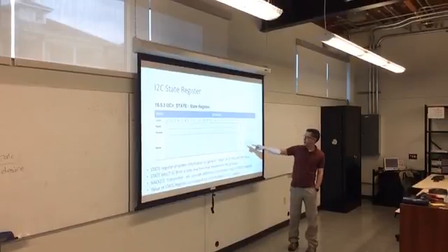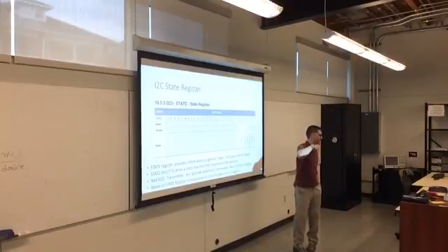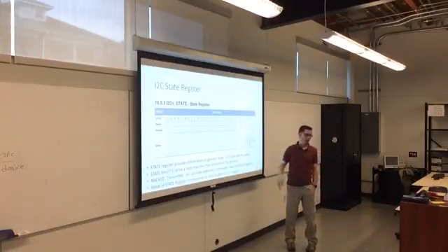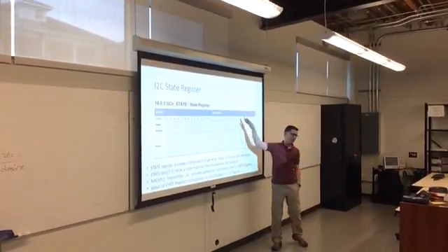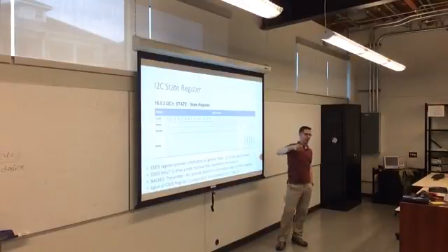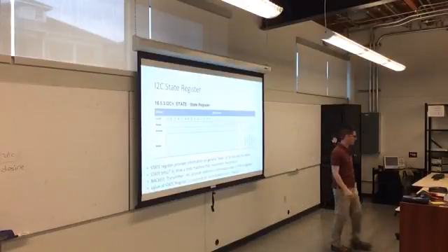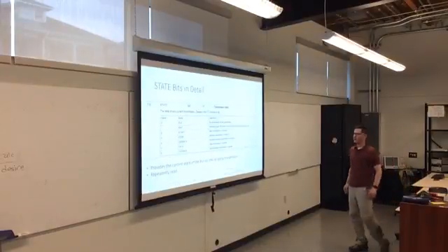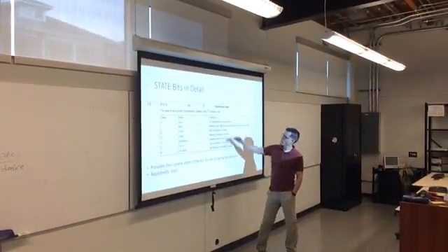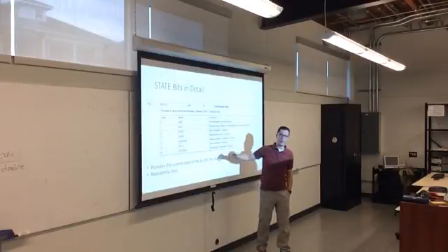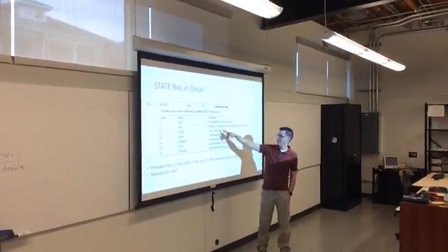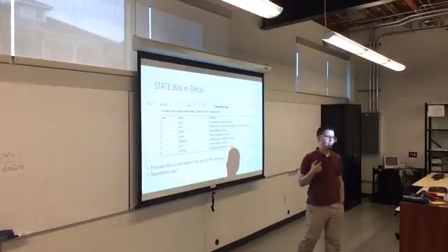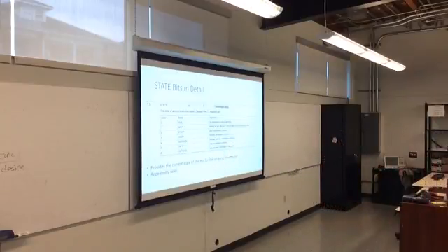And then there are 3 bits here that, in more detail, encode the state of the bus. So these 3 bits tell you exactly what's going on. So if you read this and it's 0, then the bus is idle. If you read this and it's 2, that means that a start bit has either been transmitted or received. And you're never going to be a slave device, so this will always be from the transmission perspective. So if you see the value 2 in that field, then you know you have successfully just sent a start bit.